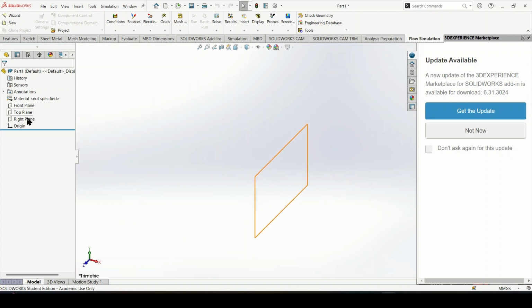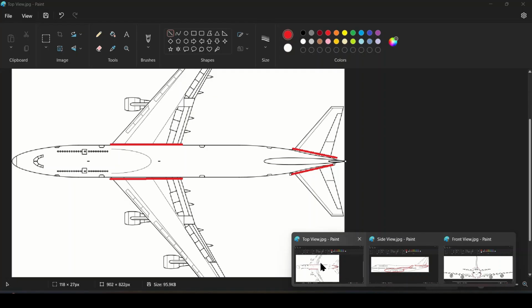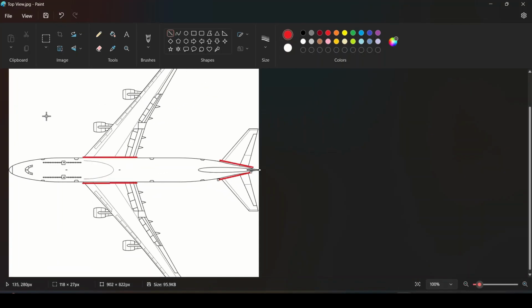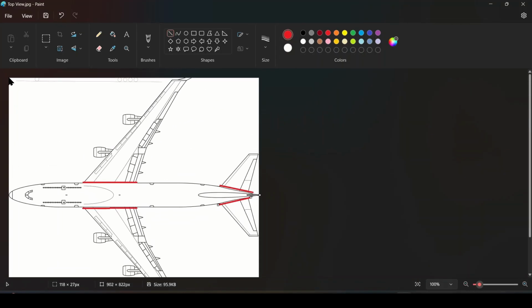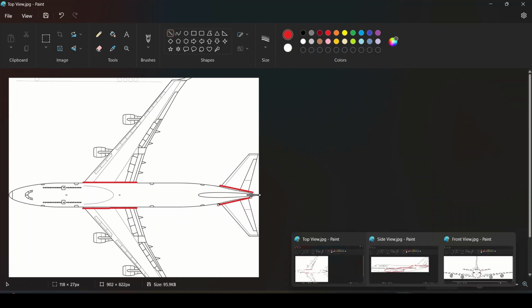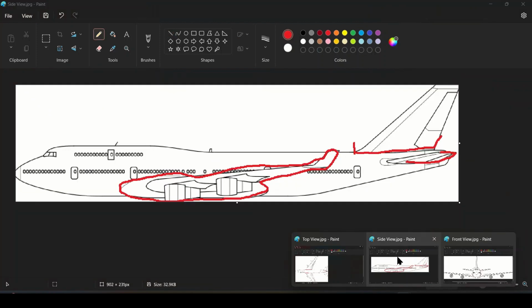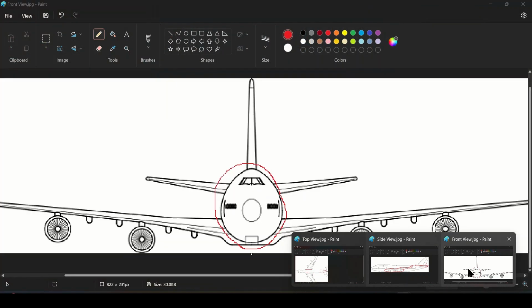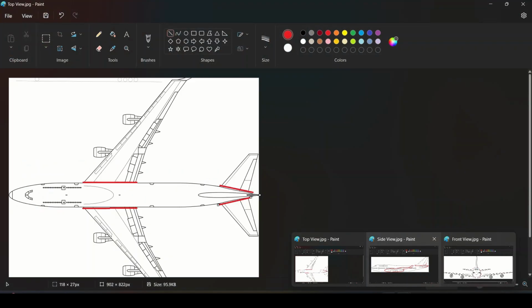And here we can see the planes and the origin. We want to make sure to remember this origin as we will be orientating ourselves with it. We want to picture the origin as the essential value that is basically in the top left corner of all these images. So if we are going to create a block down, we want to make sure it goes down in the Y direction and basically fits in the corner.